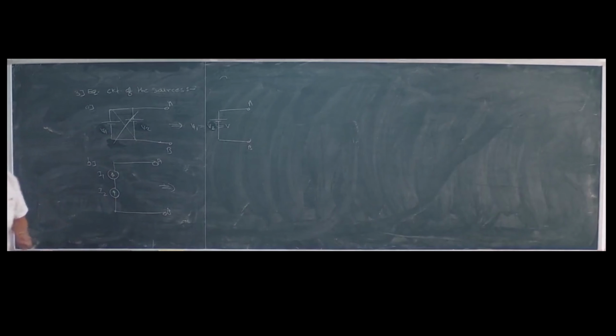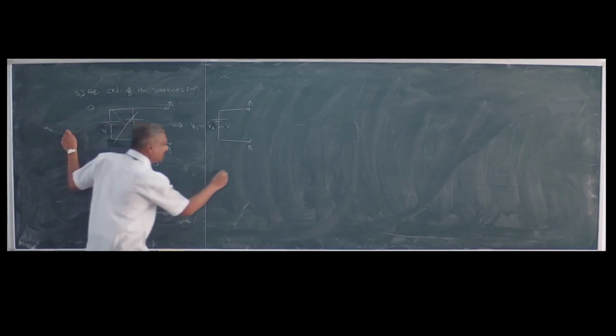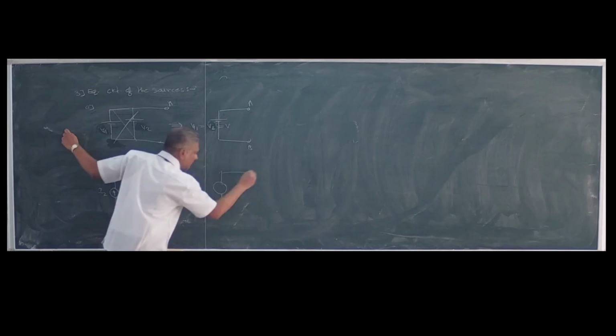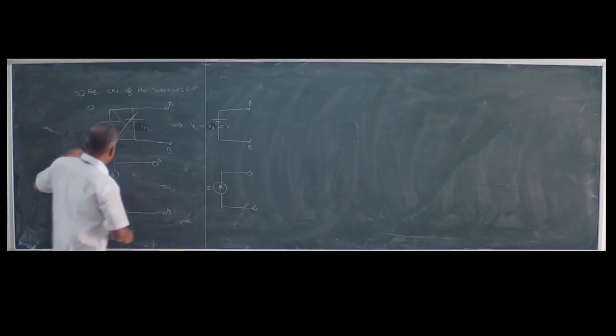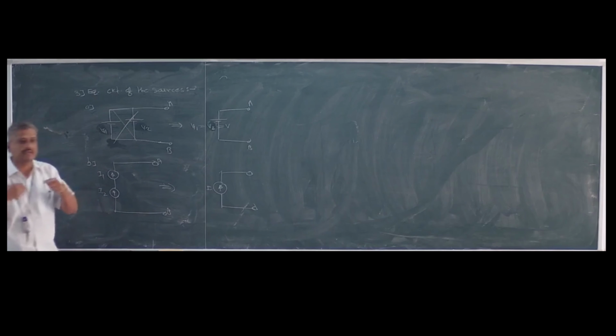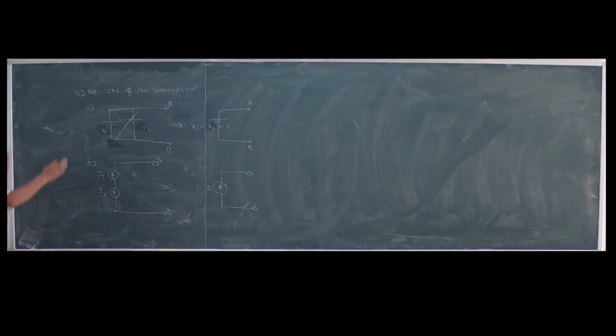Whenever we have two current sources in series, I1 is equal to I2, absolutely fine. Now here, in this case, this will be the I. And the two current sources we can connect in series only when both have the same magnitude. Are you getting me? This is the counterpart. Whenever parallel is this, what about the series? You are already aware of it. V1 plus V2 will be the series.